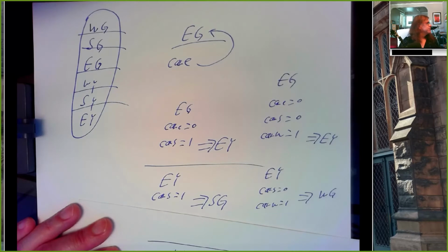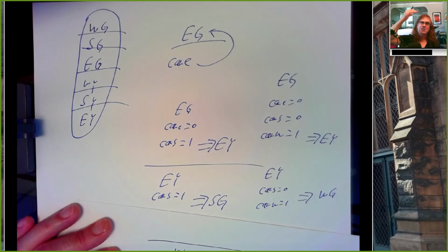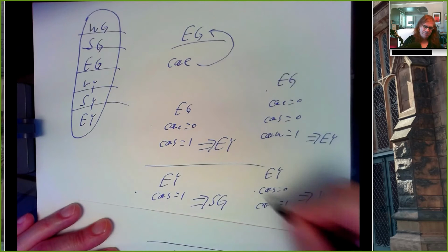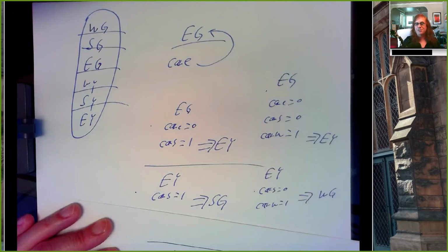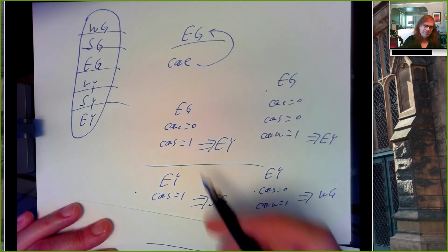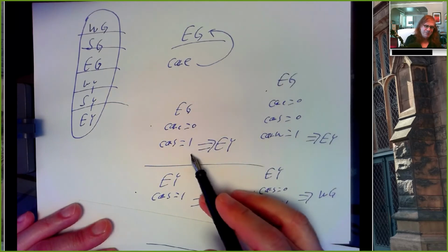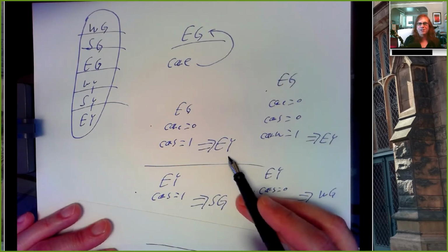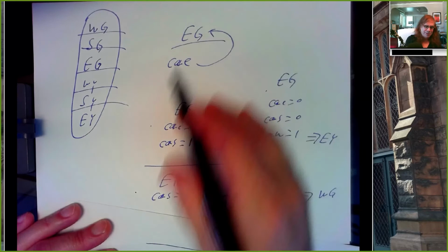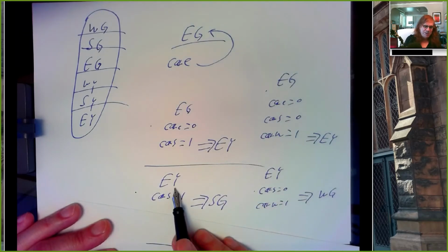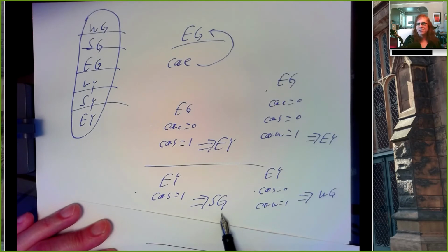So there's a 2-second clock available, and so we can use that to say, okay, when the clock ticks, let's figure out what our new state is. These conditions are evaluated every 2 seconds, so if we had a green light and a car showed up to the south, our yellow light will come on. 2 seconds later, our logic will say, oh, we're in the yellow east state, and there's a car to the south, we'll go to the south green state.